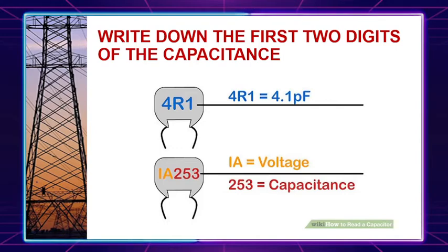Larger capacitors, such as the cylindrical aluminum electrolytic type or the double layer type, use units of microfarads, which is equivalent to 10 raised to negative 6 farads. A capacitor may overrule this by adding a unit after it: P for picofarad, N for nanofarad, or U for microfarad.